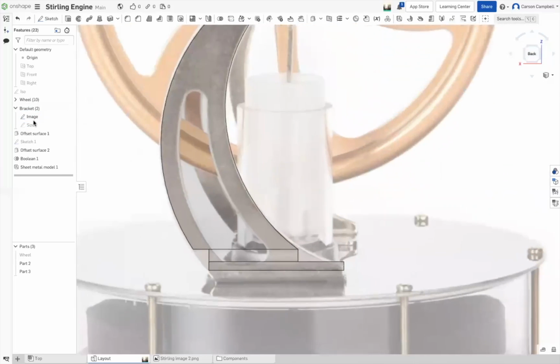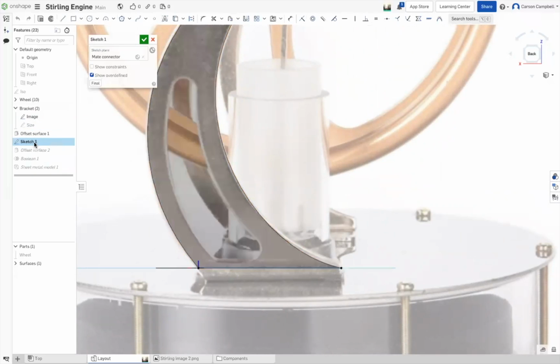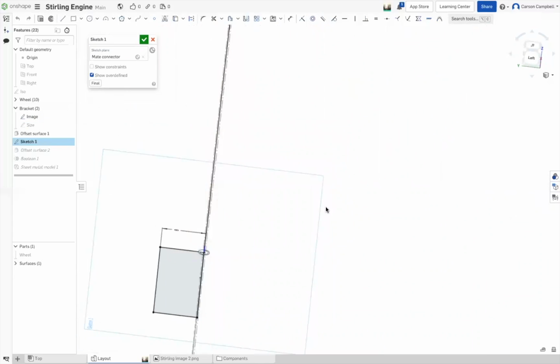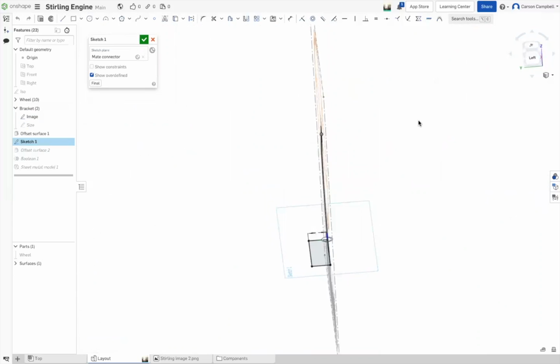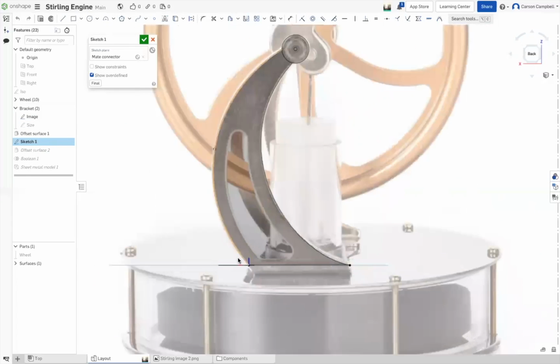The next thing you need to do is to go into sketch one, double click it, and rotate the part. Problem is that this sketch should not be coincident with that bottom edge. It needs to be dropped down. So we need to manipulate the mate connector. There's two mate connectors up in the dialog box. Click the smaller of the two.